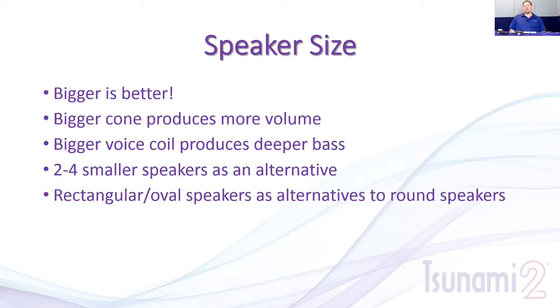Now, the other thing you want to look at is the voice coil. The way a speaker works is by sending electromagnetic pulses through the coil inside the speaker. Inside the speaker, you have the voice coil, and there's a magnet. As those electrical currents are going through, it's either attracting or repelling from the magnet, and that's what creates the speaker to move the pressure back and forth. So when you look at the bigger voice coil, typically it's going to have a much stronger presence and power when you get the electromagnetic field going, and so it's able to travel a lot farther. And again, you want to look at the bigger magnet too, and the bigger magnet size is also going to give you a stronger attraction and repel of that power.